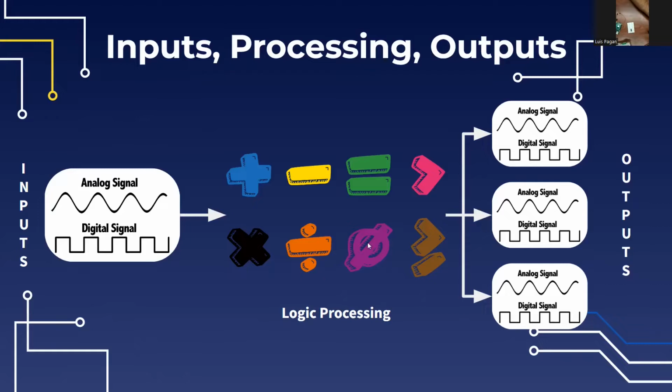If I'm checking for when it's pressed, I'm going to evaluate that logic and then output what I want to do based on that input. So let's say I wanted to output a 1, for example, as a digital signal, or high, when I press the button. I'd be checking if it's pressed, and then I would output the signal that I want.